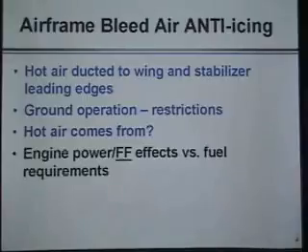In any case, you have to take into account weather. You have to take into account anything that's going to increase your fuel flow. If you look at the weather and it says you're going to fly through forecast icing, do you need to put the fuel on board in order to be able to run your airframe anti-icing system?